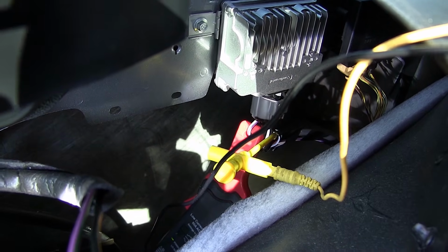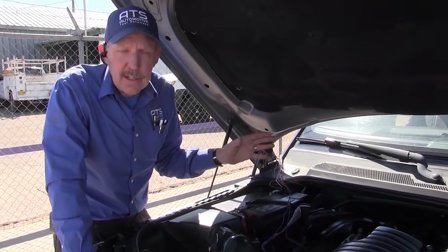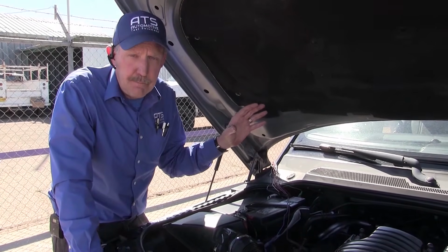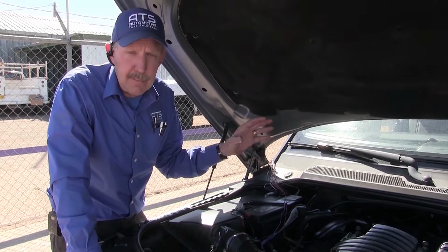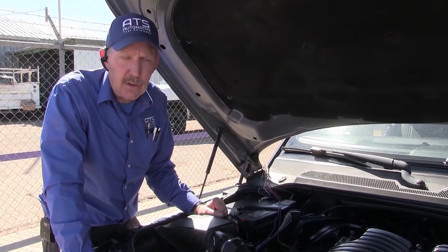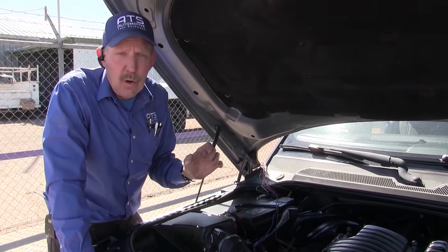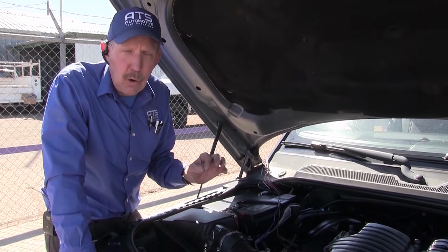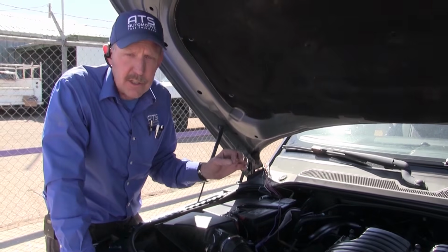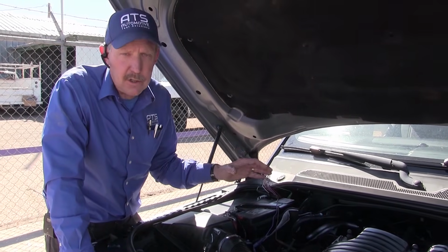I've connected channel 1, the amp clamp, on the fuel pump control module on the main power wire, and I've connected channel 7 to the duty cycle that's going to drive it. The main thing I'm interested in is the low pressure, so channel 2, red, is on the low pressure sensor for the low pressure fuel.